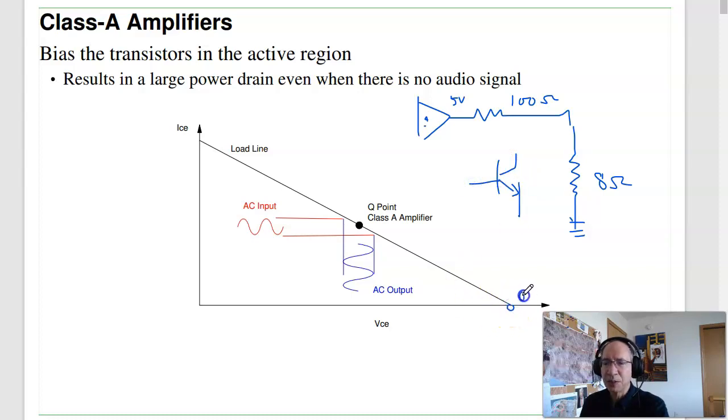At this point, the transistor's off. At this point, I'm saturated. In digital electronics, those are the 2 points one operates at. It's either going to be off or on. And if you're a Star Wars fan, like the Sith Lords, it's black and white, for me, against me, on or off, nothing in between. And I need that because I'm going to be saturating a transistor.